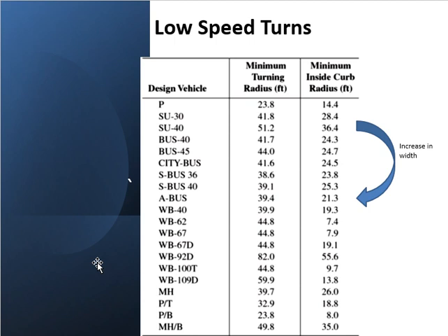Inside edge. This is the radius of the inside edge. Then what is this one, the middle one? Radius of the center line. Okay, so you have the inside edge and you have the center line. You take the difference, what do you get? If I take the difference of these two values, I'll get half the lane width, right?